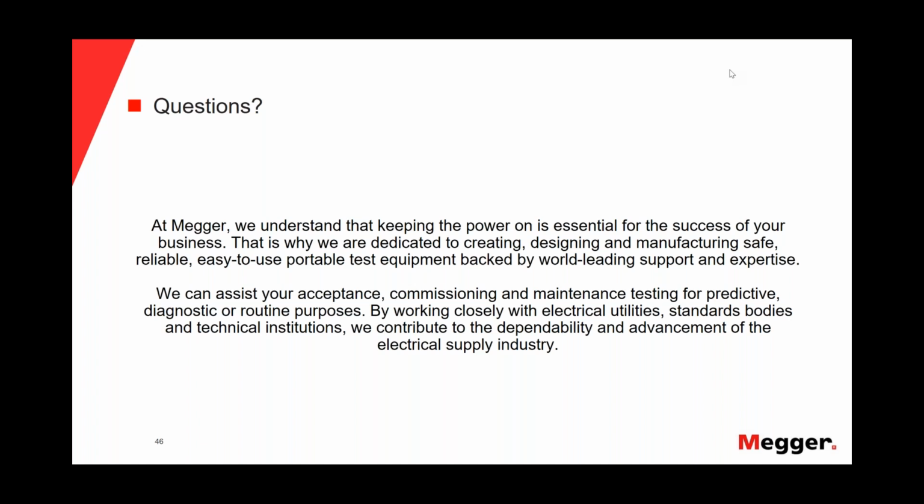I think Javier made a very important point there. It all depends how the cable was stored. We participated once in a test of a cable manufacturer who had retrieved service-aged cable from the field, and he had the same batch of cable in his own inventory still, 15 years later. But those cables had been stored outside, down in Texas. And the cables that were stored outside, even though they had never been in service, were aged much more compared to the cables that had been in service.